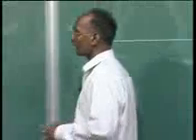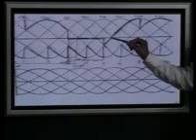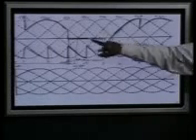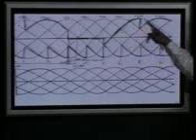You can see here in the valve voltage, in this case this valve is experiencing positive voltage all the time except during this period. So this is a negative voltage appearing across valve 3. When it is conducting it doesn't matter, but in the remaining period it is positive. That's why inverter operation is a big deal, because whenever there is any spurious signal, the valve may conduct.